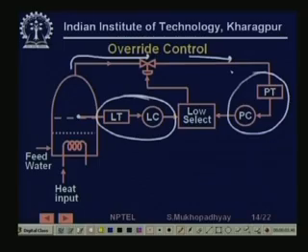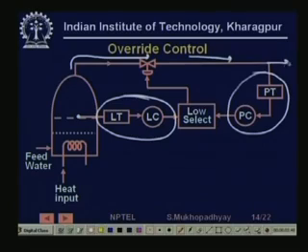So you have 2 different control loops, and which one takes precedence in a given situation depends on the state of two variables. That is happening because it is essentially a protective scheme, because the controls coordinate. How much steam will finally be drawn here is not within the purview of this controller. Similarly, how much feed water is going to be fed in is also not within the purview of this controller.